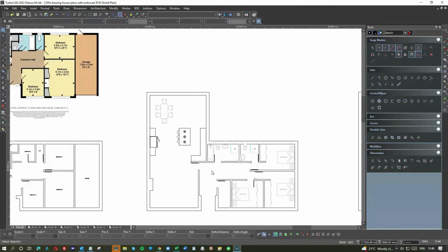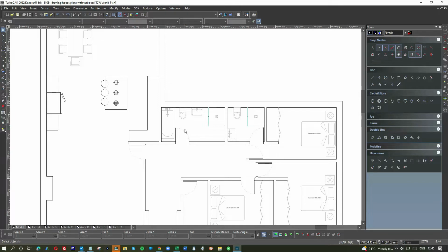So if we go back into the hallway now, whereas before we had an old-fashioned bathroom and separate loo, here we have a much better family bathroom, which is standard size, 1700 long, 700 wide. Generous size for the actual WC and the basin, or basin and pedestal. It depends how you want to do this. You can work this a whole range of different ways, but generally speaking, that's the space allocated for a loo and for a sink.